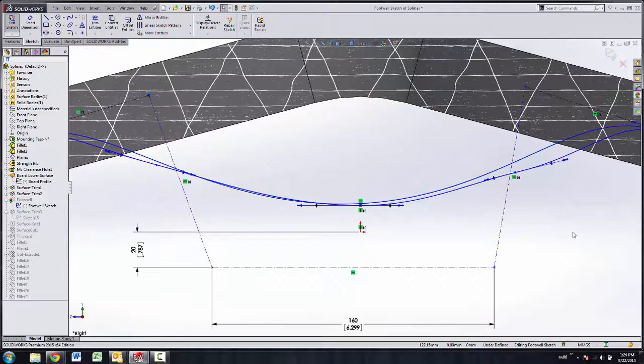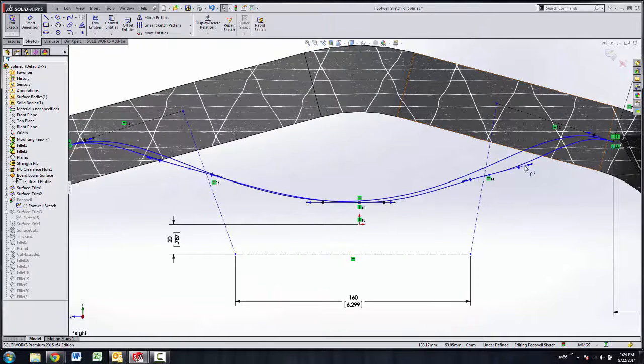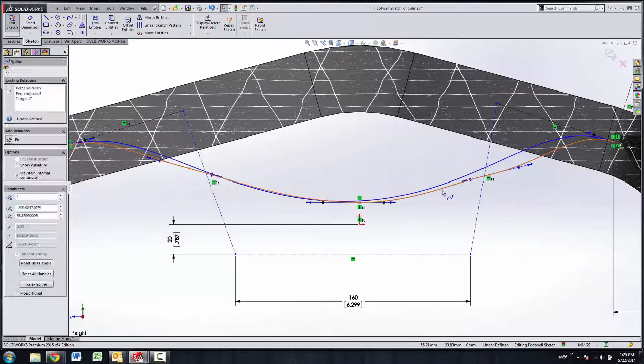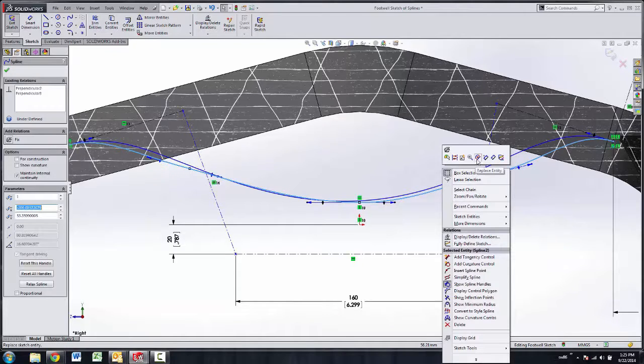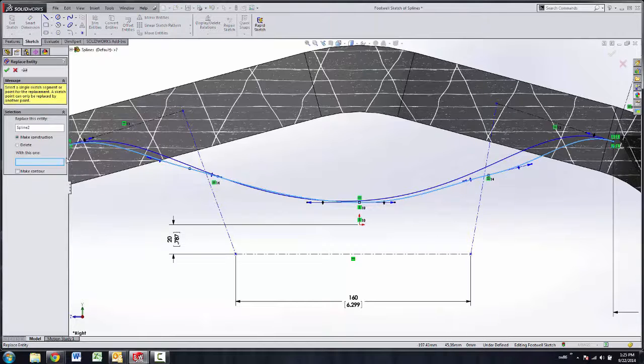and make it into a solid line. So all that other swept geometry, the fillets, all the other entities that were actually children to this parent entity right here will now be switched over to this new entity by using the entity replace command. You can find it right here when you right click in the menu, and this is how it works. If I go to the replace command, I can go in there and replace this with the new entity.